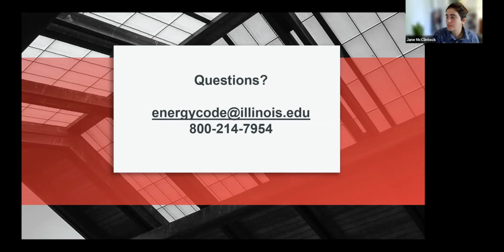We had a question come in. An attic was converted to an addition with the vaulted ceiling completely. I think this is relating to the previous question. Okay. So yeah, again, for a Manual J, you would enter in the full building for the sizing of that for Manual J's purposes. For code compliance purposes, it kind of depends what was done there, but the converted portion of the building would have to be considered for the code compliance portions. The base floors of the building would not be included in that code compliance analysis.